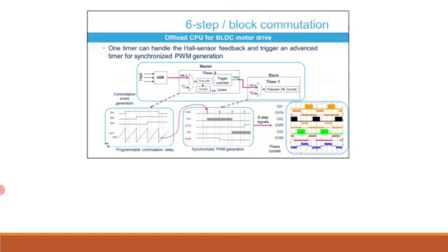The transition from one step to another is preloaded by software in the communication interrupt routine and automatically transferred by the hardware to reprogram the output operating mode when the next communication arrives. The figure at right shows the 6 PWM signals for 2 consecutive complete 6-step sequences together with the current in one of the motor phases.